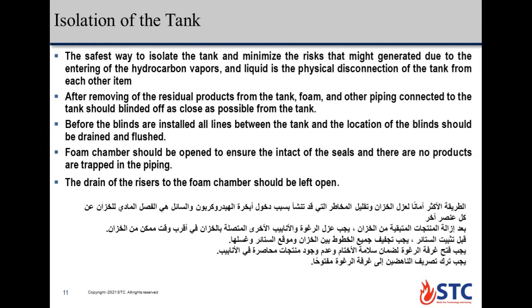Okay, 3, before the blinds are installed, all lines between the tank and the location of the blind should be drained and flushed. Foam chamber should be opened to ensure the integrity of the seals and that no products are trapped in the piping. The drain of the riser to the foam chamber should be left open.